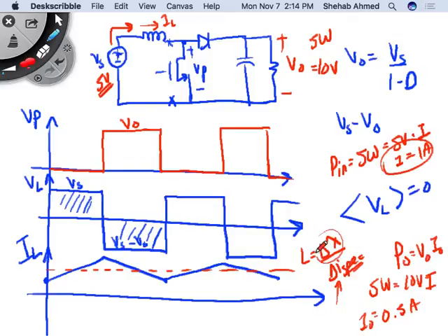And then how do you calculate delta lambda? Integral. The area under this curve. You know your duty cycle, and you know your switching period. I mean, this is something you have to choose. You have to select a switching period or switching frequency, or you are going to be given a switching frequency, and then you will iterate. Okay, this is not okay, I can go higher. If you go higher, you have to change your inductor value again and iterate. Typically you will select the switching frequency based on the switches that you select and the power loss that you calculate. This will be an iterative process.